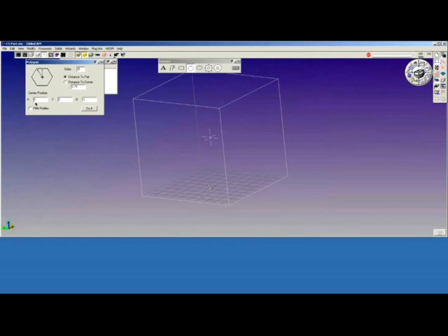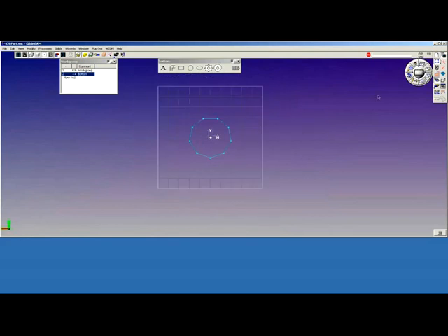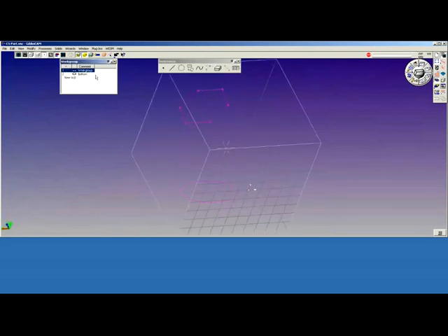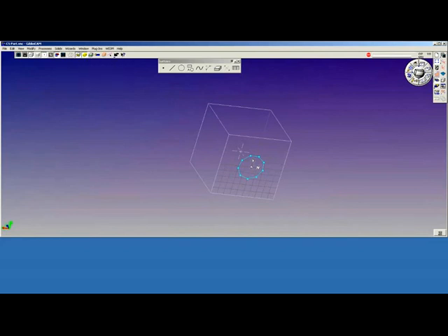Once again, you notice it's not X, Y, and Z. It's H for the horizontal axis. The Y remains as a primary axis, and the depth is the into the work axis. We'll say do it, and it creates that polygon. Home view brings it visible, and if I change work groups, I don't see that geometry. So in order to machine that geometry, I need to have my work group active to show it. And now I can go in and machine it.